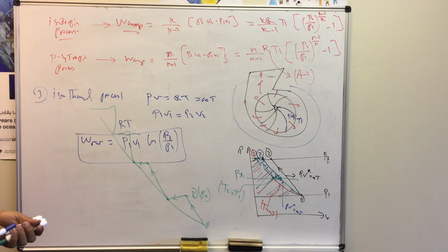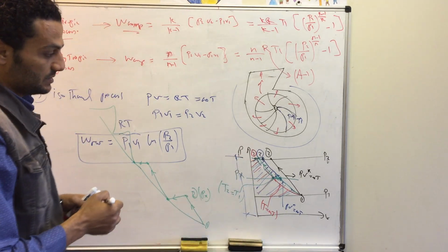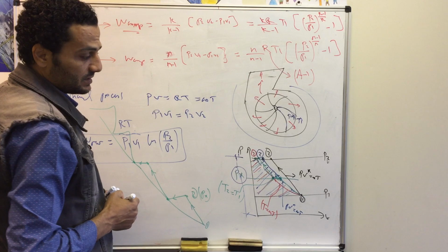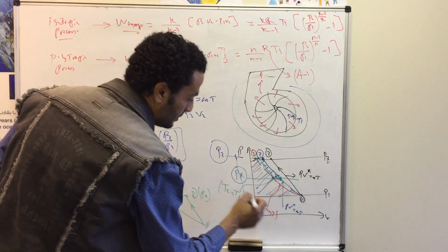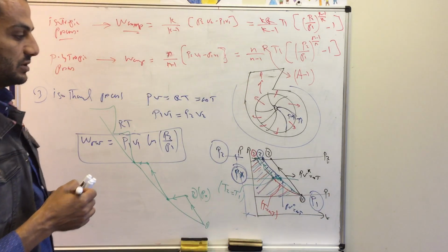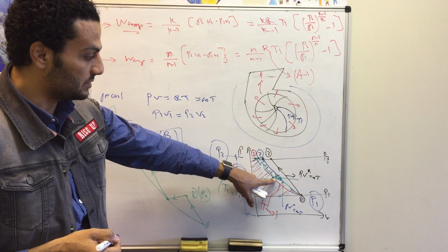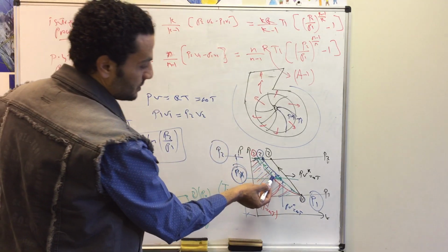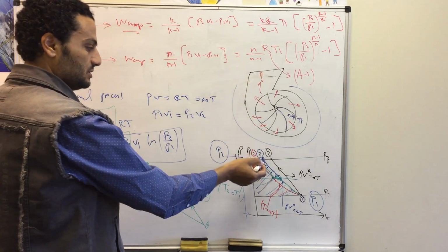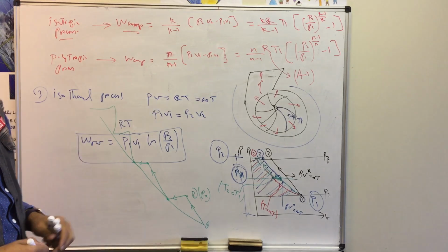Let's consider the special case when we have a two-stage compressor. So in this case, we have only two stages. We raise the pressure from the initial pressure P1 up to an intermediate pressure Px, and then we can reach the final pressure P2. The inlet pressure is P1 to the first stage, leaving at Px. Then we can cool down this gas until we reach the isothermal line. Then following the polytropic process, which is the green line here, we can raise the pressure from Px up to P2. And if we have more stages, we can cool down again up to the isothermal line, up to the initial temperature again, and then do another polytropic process.